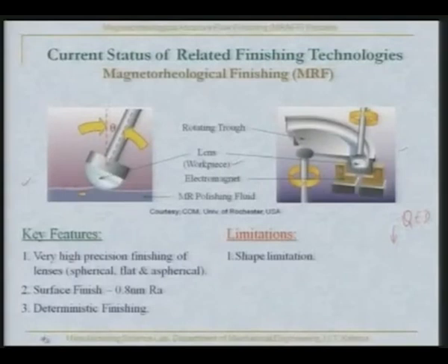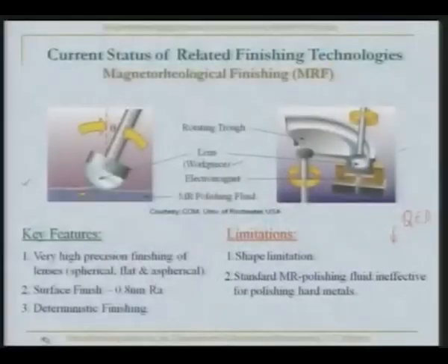There are certain limitations of this particular process. First is the shape limitation. Only certain shapes can be finished by this particular process because of the configuration of the setup. Standard MR polishing fluid is ineffective for polishing hard materials.